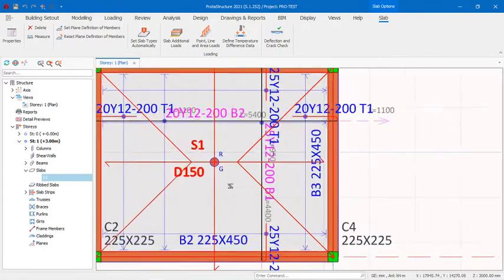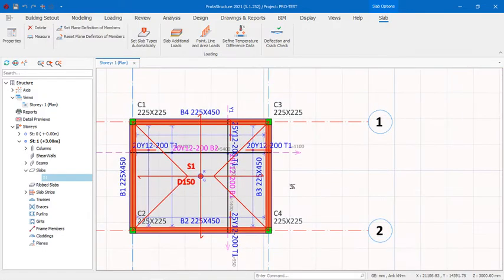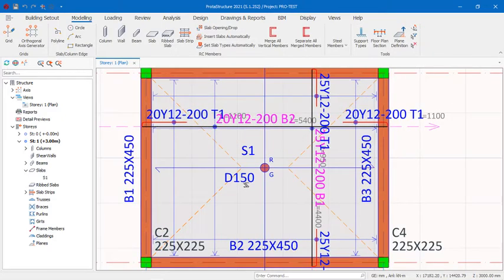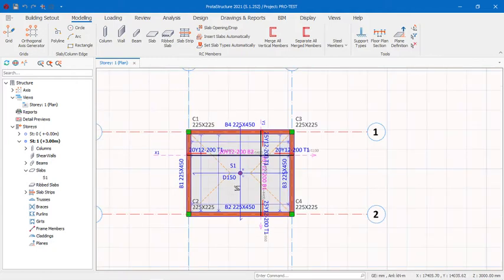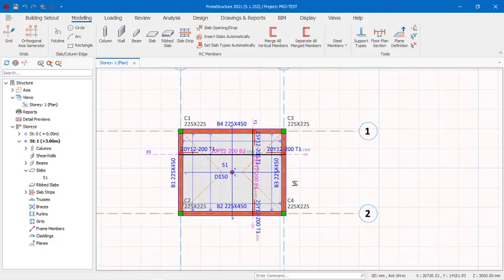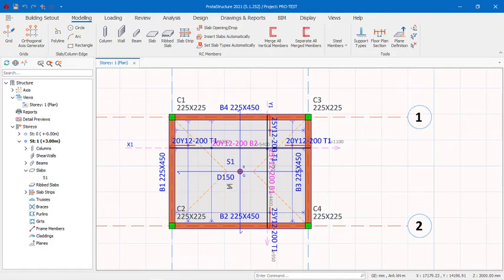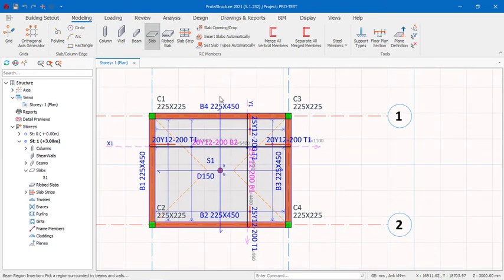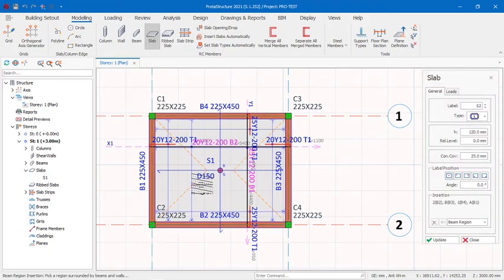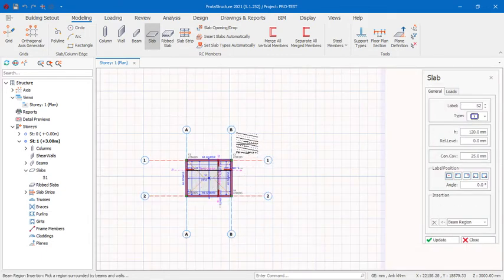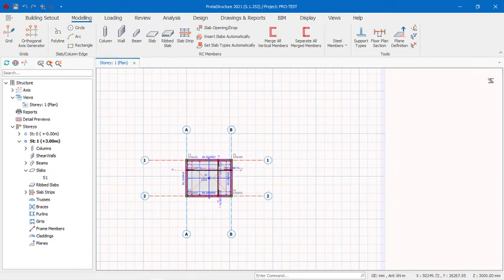If you don't do that, you risk having coefficients picked by the software that will not be what they should be, as you have not set the case for the slabs. Because by the time you click slab, it's showing me 1. So by the time I insert into multiple bays or panels, 1 is the case that is reading on it.